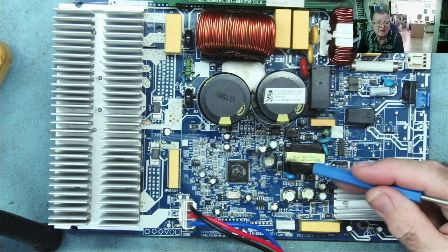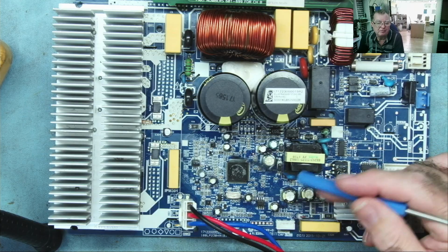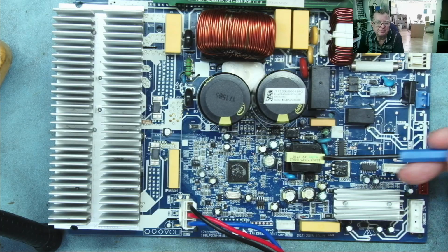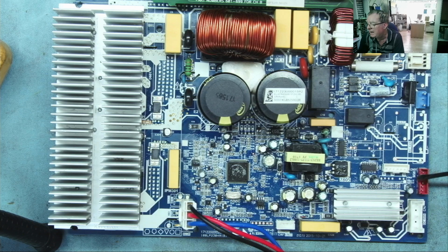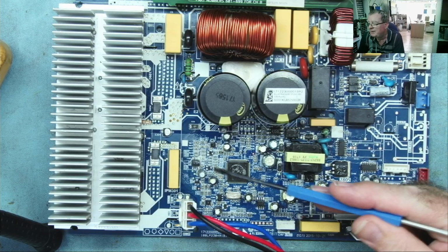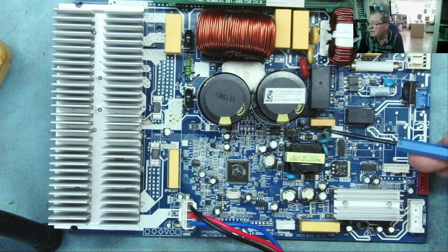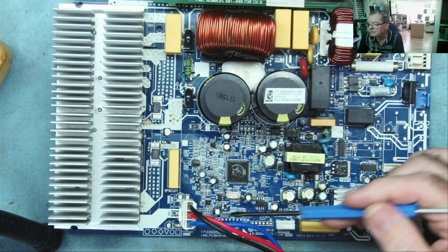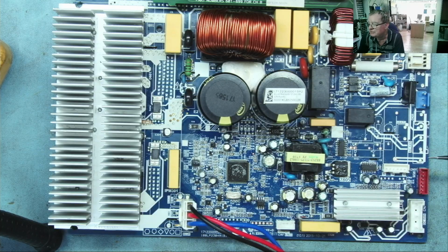So the processor itself is effectively insulated from the outside world, which means that if you have a problem with whatever this connects to, the chances are the chip which is involved in the communication is going to get it. Yeah, so common failure, especially with microprocessor control stuff, look at all the chips that are facing the outside world. And we can generally do this just by looking up the datasheet to see what the chip does.